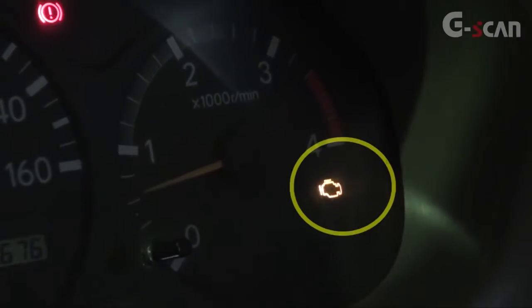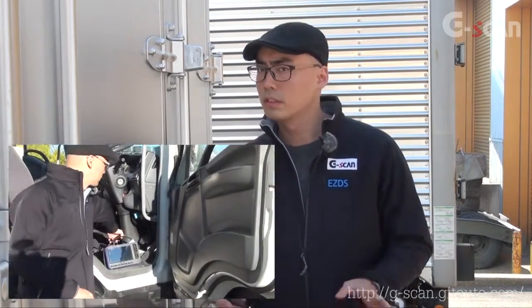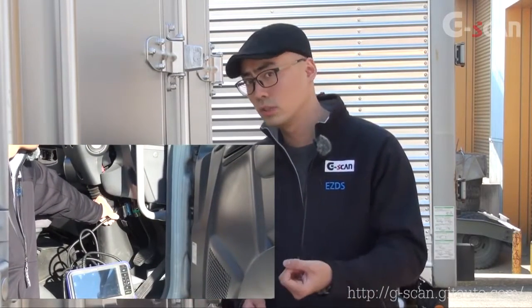Now let's talk about some basic diagnosis technique using G Scan. When you notice that your vehicle seems abnormal and suddenly the malfunction indicator lamp comes on, what would you do? Of course, you would try to find out why the MIL came on. First, you need to figure out which system is malfunctioning by reading the diagnostic trouble code. In order to read the DTC, you need to search for the data link connector location and connect G Scan. When you're set, you can go to DTC Analysis and then read the DTC.